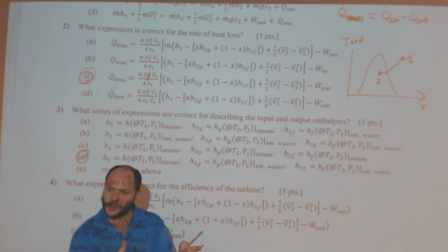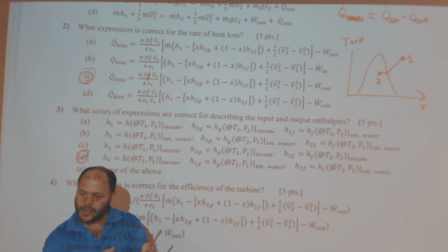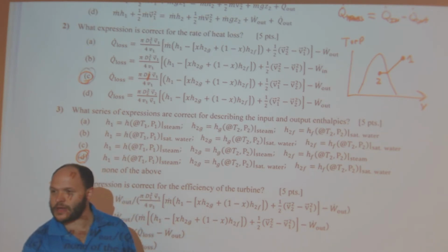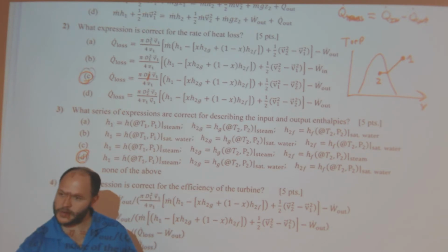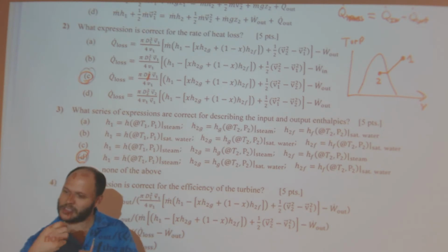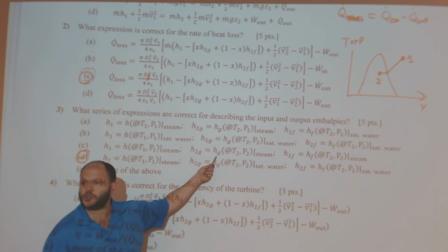But if I take a cube of water and I start boiling, and say everything is just a little cube and it has water in it, and it's at 1 atmosphere, and it's at 100 degrees. So at that point, it can be either all vapor or all liquid. If I pick a point in time, it might be 70% liquid and 30% vapor. But it's at that temperature and pressure. So you have to distinguish between the phase. But it's still saturated water. I should say saturated H2O, right?